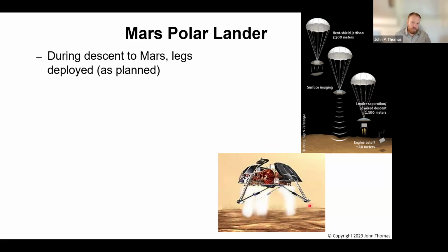And as long as all 3 agree that we have touched down at the same moment in time, the software has a really important job: to cut power to the descent thrusters. It will command them to turn off. And that's obviously important. You don't want this thing to bounce up or flip over. We'll lose the mission on Mars. So here's what actually happened.